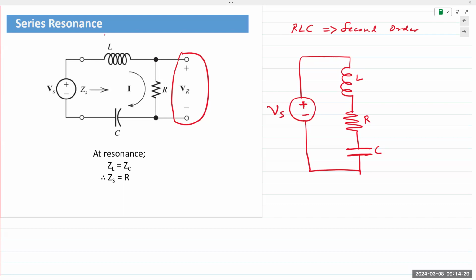Capacitor is exactly the opposite. It is similar to the inductor, meaning it can receive the energy and send the energy back out. But it's the opposite of an inductor because the current leads the voltage. The capacitor will actually receive the energy in the negative half cycle and send it back out in the positive half cycle. So it's the exact opposite of the inductor.